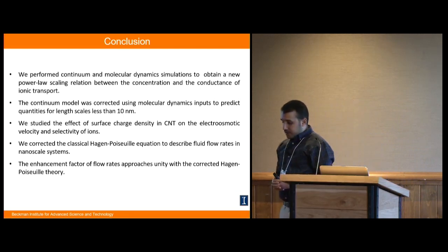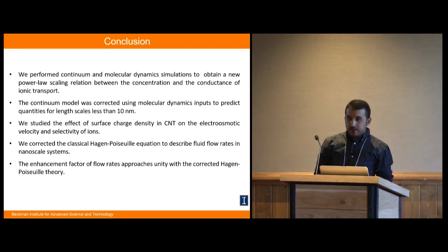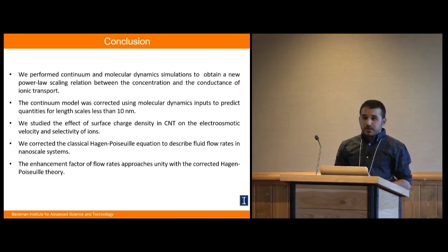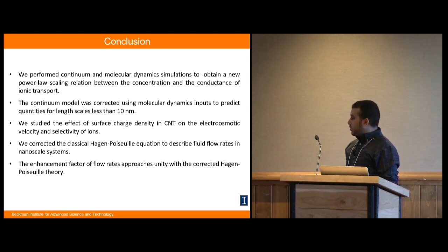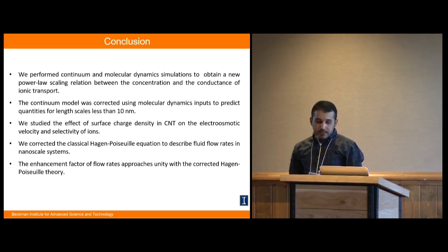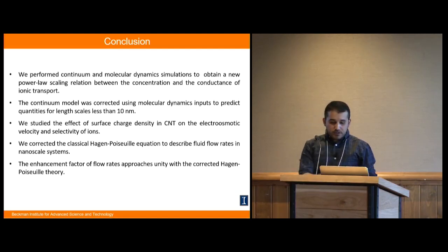I have talked about a new scaling of the power relation and ionic conductance concentration relation, and how we corrected the continuum approximation using molecular dynamics. I also talked about correcting the Hagen-Poiseuille equation and how our enhancement factor approaches unity with fitting the viscosity and varying the friction coefficient.